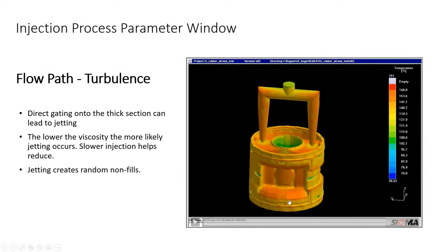And you can see that in the finished part by looking at the temperature and all the muddle. We have green and orange, we have the whole spectrum mixed together, because what we're seeing here is the mixing of the material created some temperature variations throughout the part. Where we see temperature variations, we're going to also see defects, mold lines. We're going to see knit lines. We're going to see a lot of different types of issues due to that turbulence.